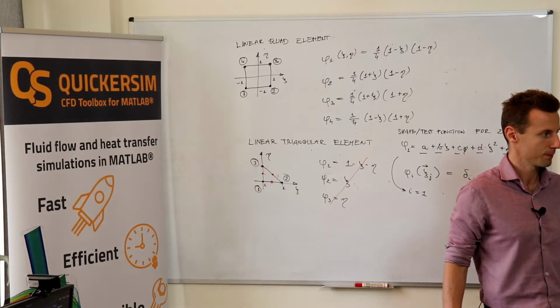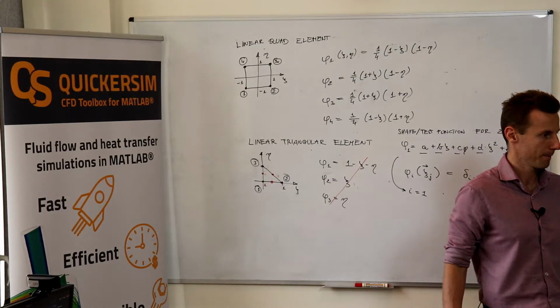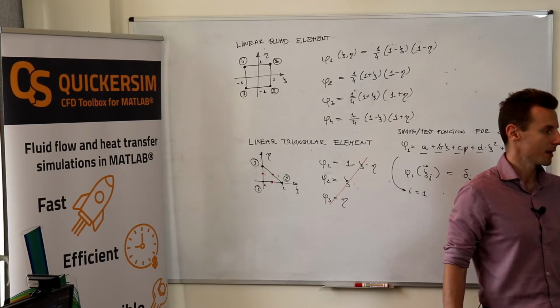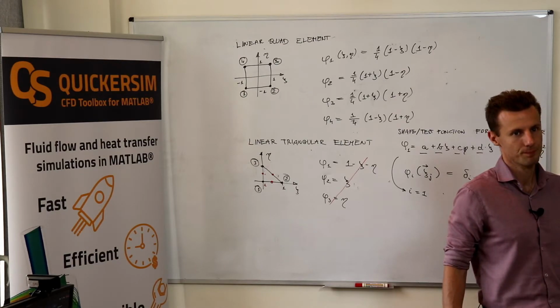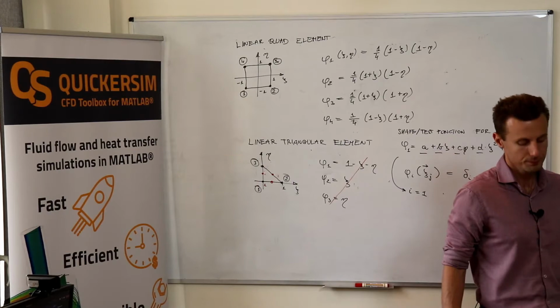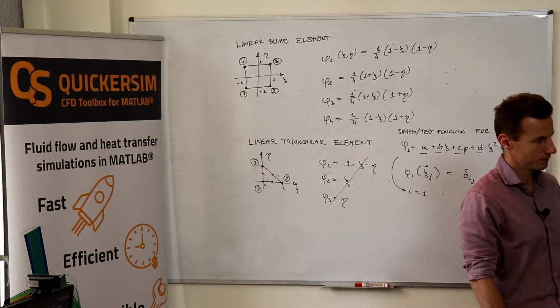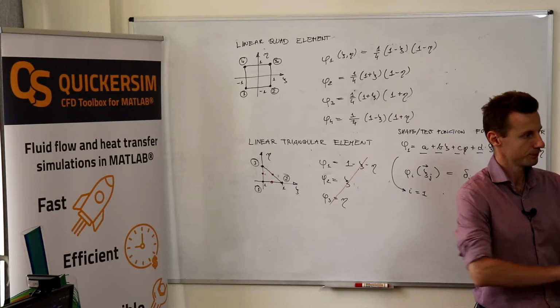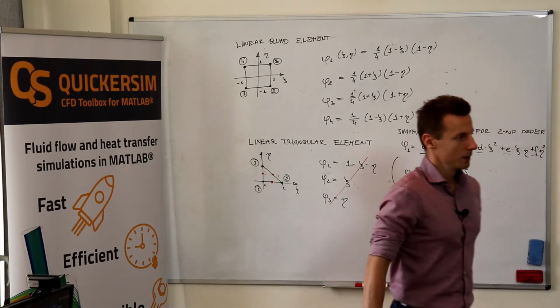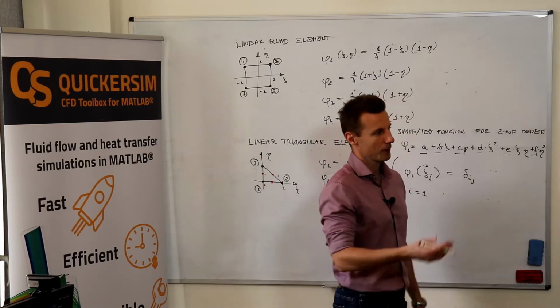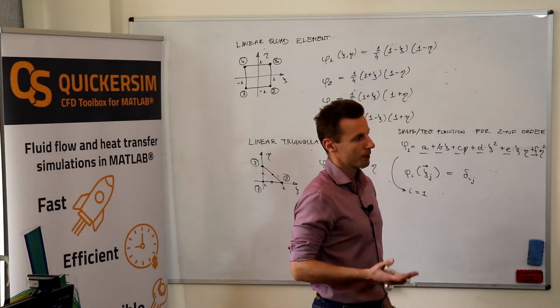Are higher order methods feasible for complex geometries? Industrial geometries? I think it depends. I think there's a problem with generation of that much. There is. With increasing order, you have to have fewer and fewer elements, and if they are geometrically linear, they are not able to represent geometry.